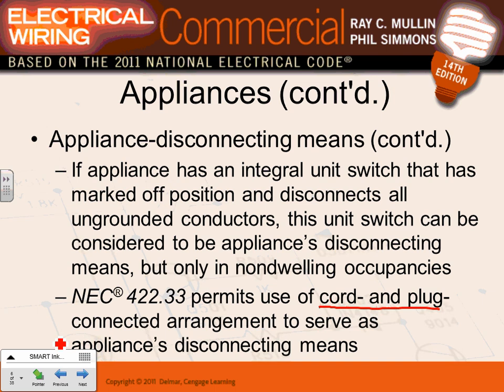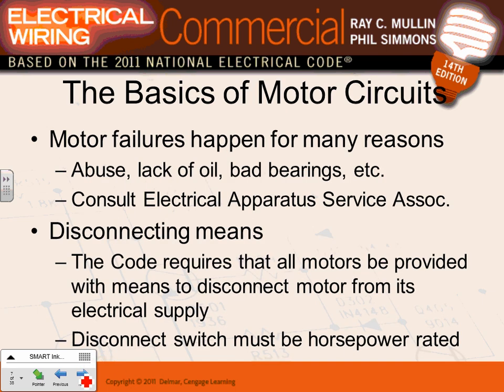When you guys were laying out your mechanical equipment, do you remember what we were doing? When you're reading through a spec, it always emphasizes one thing: disconnect, or starter with disconnect. Do you hear the word disconnect all the time? For safety, all machines, all equipment must have some type of a disconnect to isolate them, to work on them safely. So that's a couple of things about disconnects. Okay.